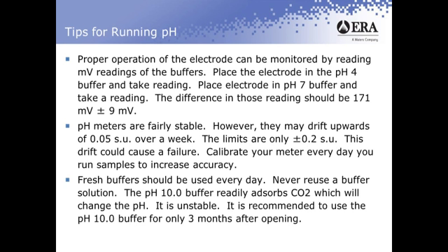The next thing I'd recommend doing is using fresh buffers every day. The importance of using fresh buffers is that you want to make sure that you're not changing the pH of your buffer solution, which can happen if your buffers aren't fresh, so that you maximize the accuracy of your testing. I would recommend to never reuse a buffer solution. The buffer solutions themselves are very inexpensive as far as testing goes.